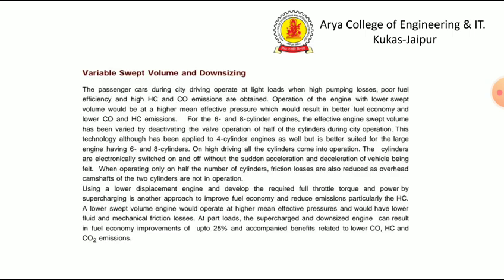Variable swept volume and downsizing. Passenger cars during city driving operate at light loads, when high pumping loss, poor fuel efficiency, and high HC and CO emissions are obtained. Operation of the engine with lower swept volume would give higher mean effective pressures, which would result in better fuel economy and lower CO and HC emissions.